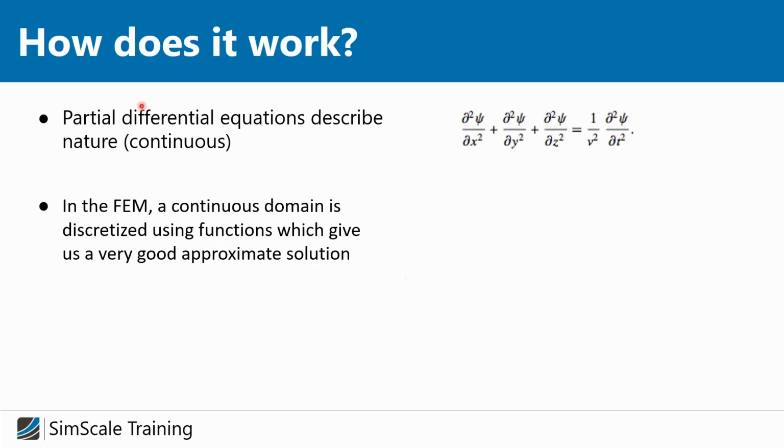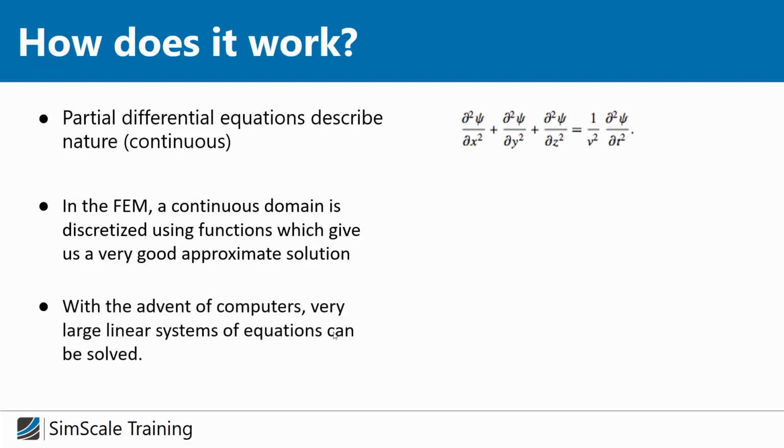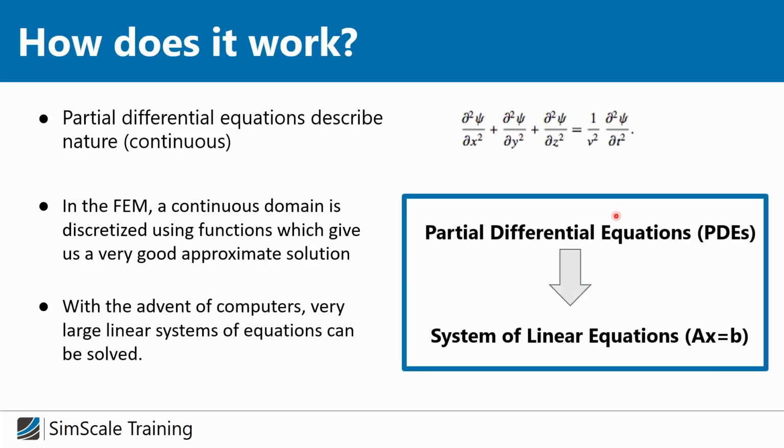And when using FEA, what we basically do, we take these equations we cannot solve for a complex real-world problem, and instead of solving them analytically, we use a discretized function which gives us a kind of approximate solution. And this process is basically the key or the fundamental idea of finite element analysis, because it allows us in the end to convert a very complex problem into a system of simpler problems, a system of linear equations, in contrast to these partial differential equations we cannot solve.